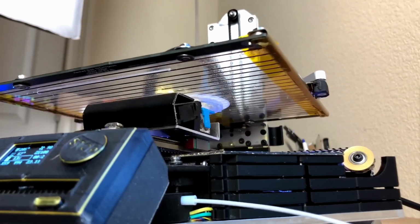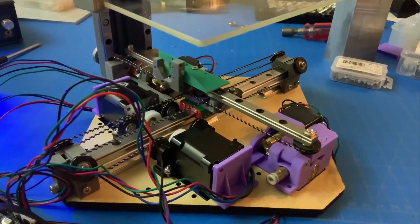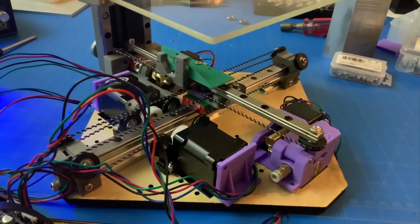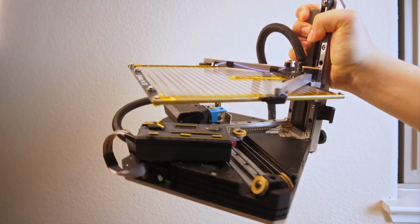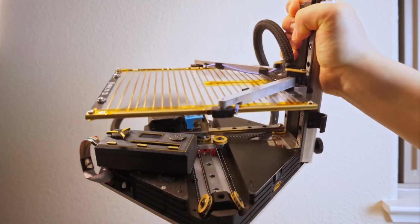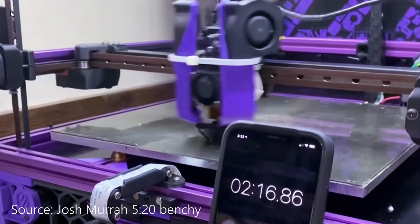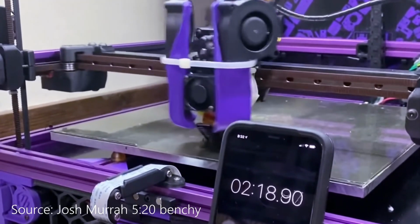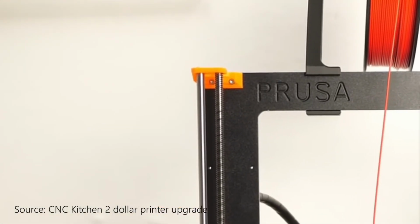So to answer the question in the title, why is this printer upside down? Well, the main reason is maximum stability at minimum weight, which is essential in a portable 3D printer. Keeps the gravity down low. 3D printer heads are not light, and they are usually being swung around by the motor at high speeds and accelerations. As a result, this can cause the whole machine to shake.